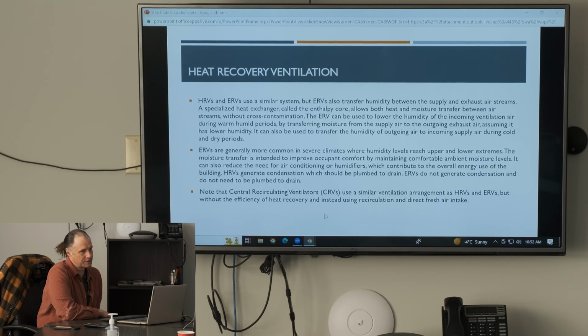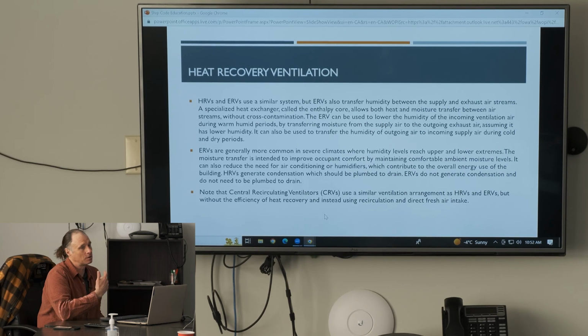No, it wouldn't change the efficiency of the actual heating system. Or the efficiency of the HRV either. Right, exactly. They're still going to be operating at that 65 to 85%, which is also taken into account in those step code metrics that are used by the energy modeler.